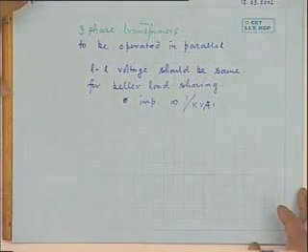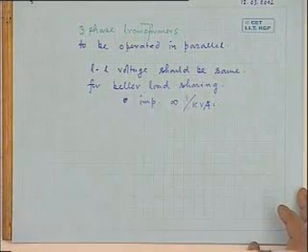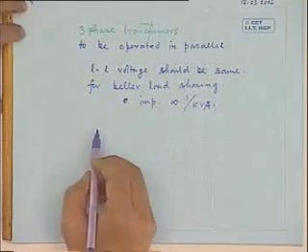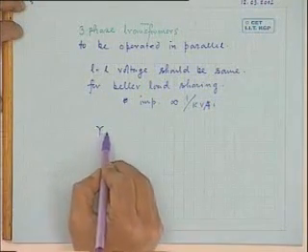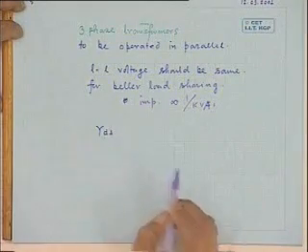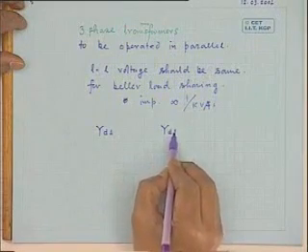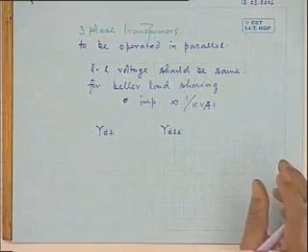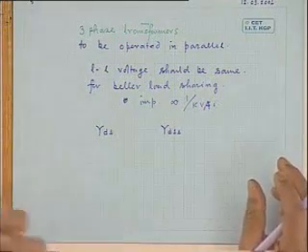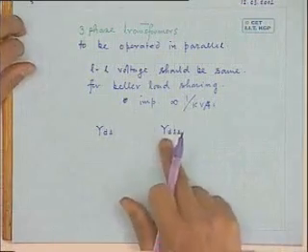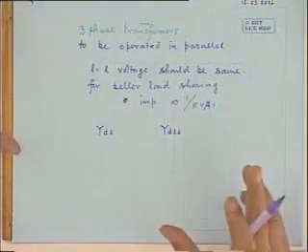But important, another additional point you should remember. Can you tell me what, in terms of the transformer connection groups? Suppose I will ask it in this way. Suppose you have a transformer YD1. Can I connect it in parallel with YD11? In spite of the fact that the RMS value of the line voltages on the primary side and RMS value of the line voltage on the secondary side, they are equal. But will you allow this to happen? Certainly not, because the magnitudes of the voltages are same, but they will be shifted.